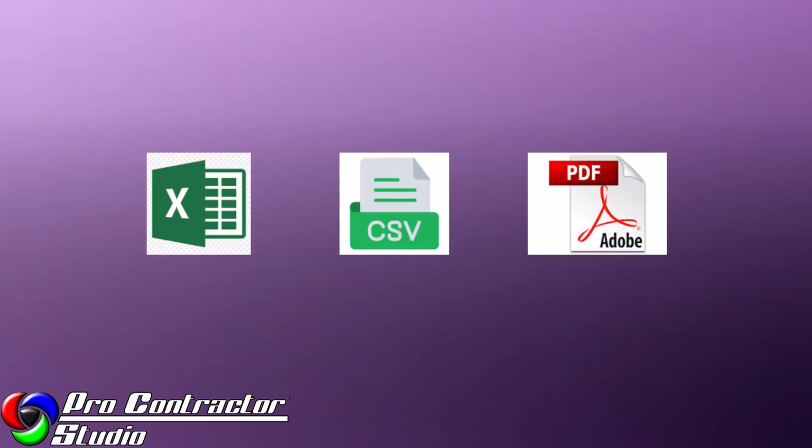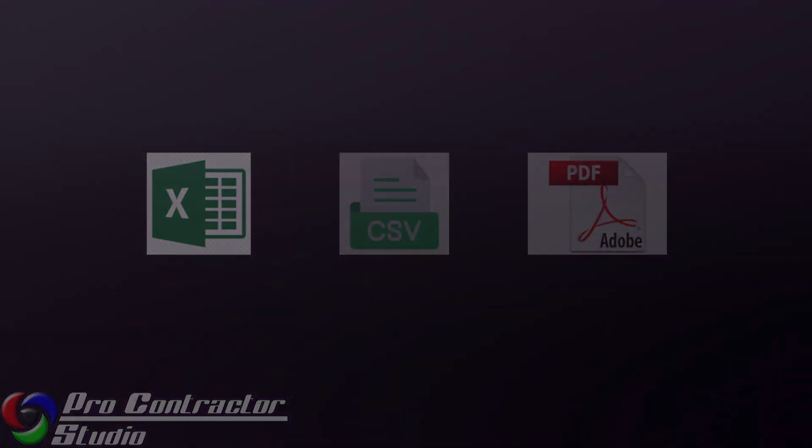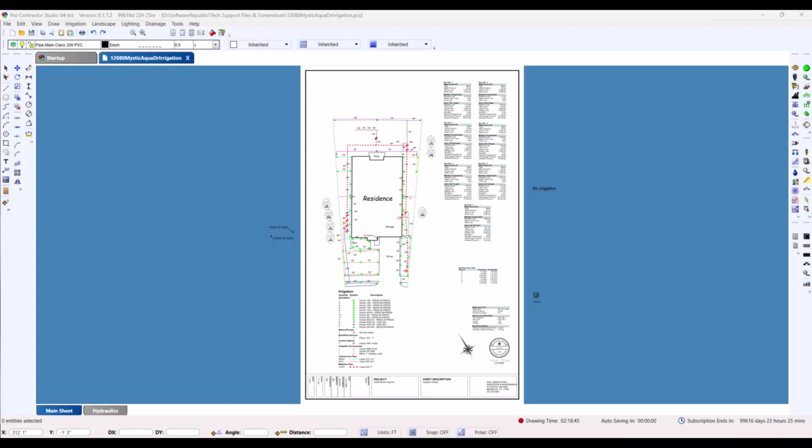Material lists, takeoffs, and estimates can be viewed on the screen, sent to a printer, or exported into Excel spreadsheets, CSV files, or to a PDF. To create the material takeoff or estimate, first make sure you have the file you'd like to create the material list for open in ProContractor Studio.